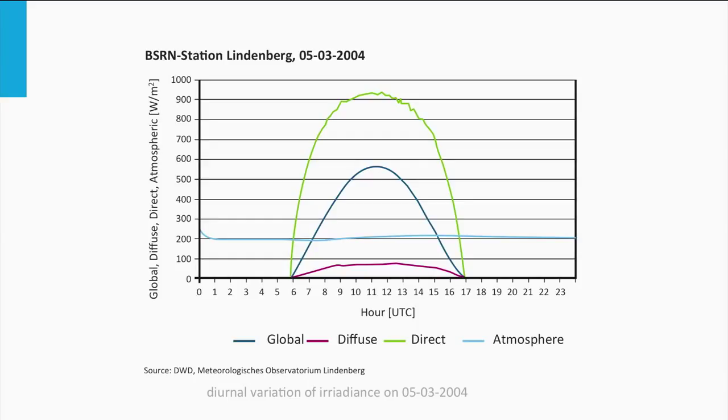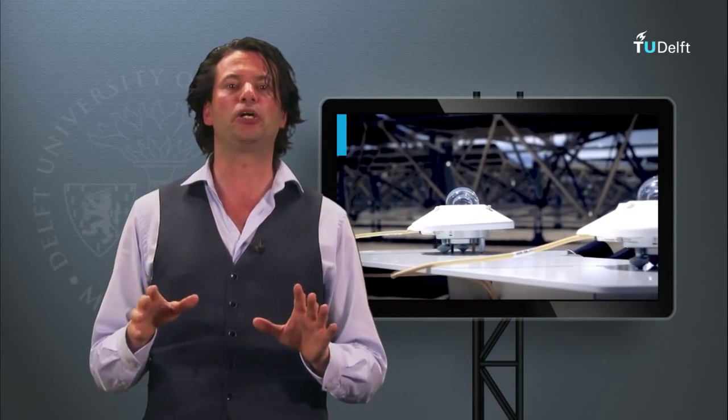In weeks 7 and 8, we will talk about PV systems. You have to realize that the response of a PV system differs between diffuse light and direct light. This week, I would like to show you how we can measure the irradiance of direct light and diffuse light. For that, we use a pyranometer, and you often see these tools installed next to a PV system.